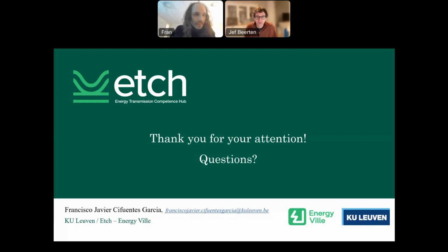So Armando also asks if it's possible to extract the frequency response from Simulink EMT models. Well, it is possible, but this tool is not intended for that. It's intended for PSCAD mostly. I am aware of the people at AEMO in Australia. I think they have a similar toolbox for Simulink, so it is certainly possible, and perhaps they will also open source it soon. We don't know, but in any case, the same methodology can be applied in Simulink.